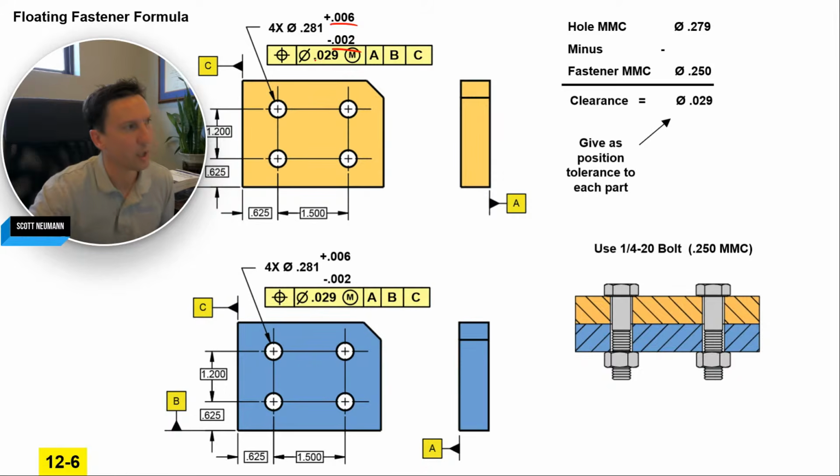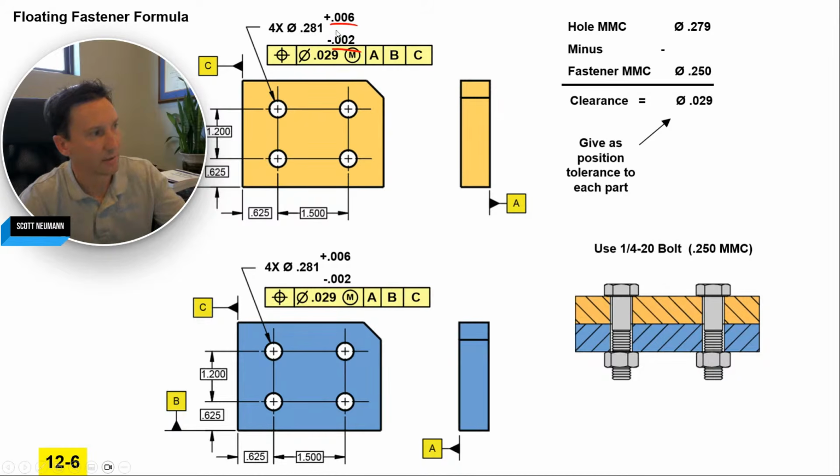Okay, so then you look at drill charts, and they'll recommend a little more plus than minus usually on drilled holes. It's because when a drill becomes dull, it tends to walk and wobble in a hole. So giving the tool more life by giving it more plus than minus. That's what we have, standard drill size and recommended standard drill tolerance there.